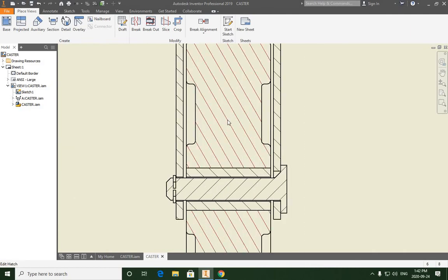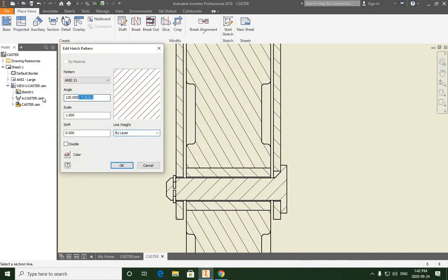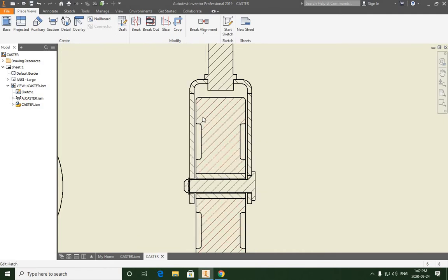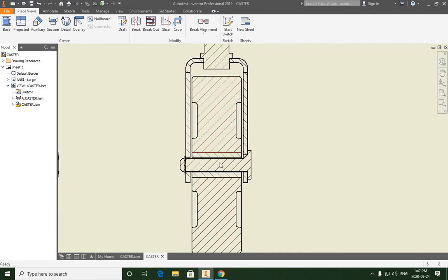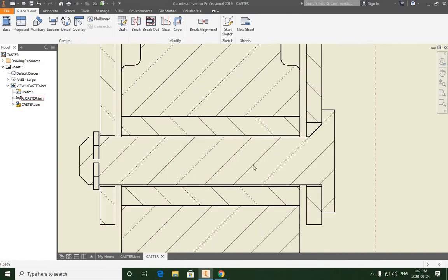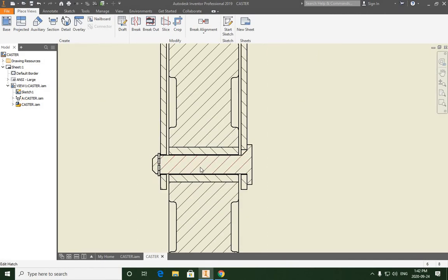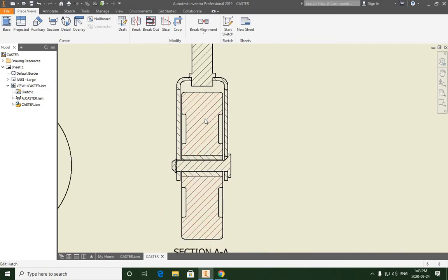And we want our wheel to be 45 degrees. So the idea here is every time a sectional view of an item is up against another item, that section line needs to be reversed. It needs to be a hard 45-degree reverse. Now the reason for this is so we're not confusing this to be all one item, right?